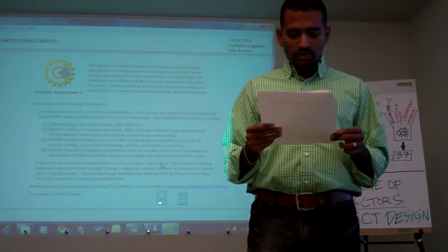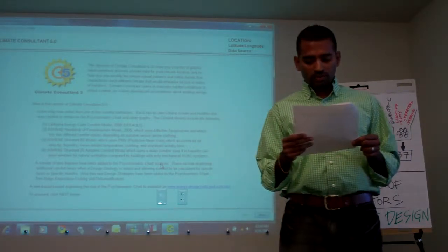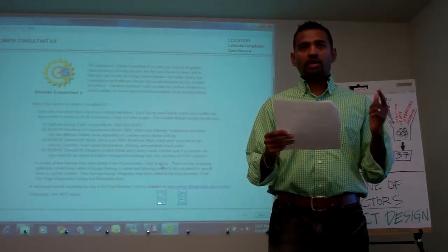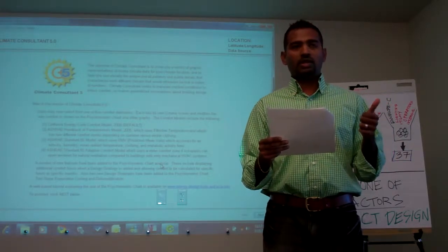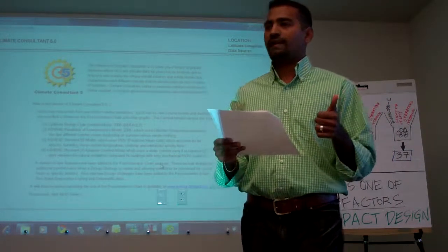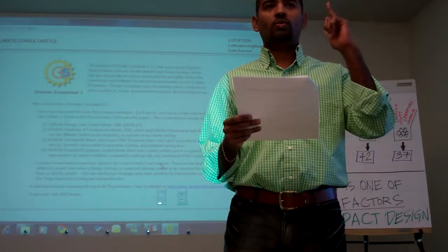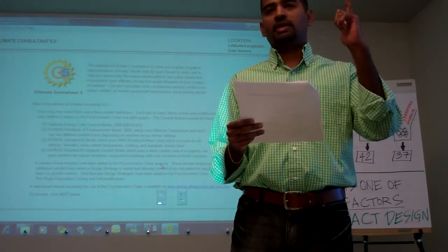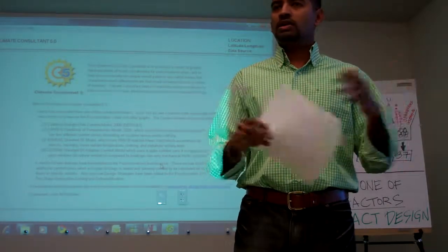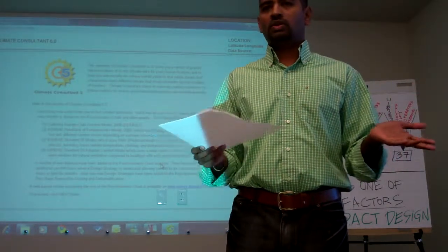To determine ways to reduce EUI of your design, what is the most important idea to keep in mind during the energy analysis process? Change one variable at a time. Because if you change more than one, there's no way we can understand what is going on with the building.